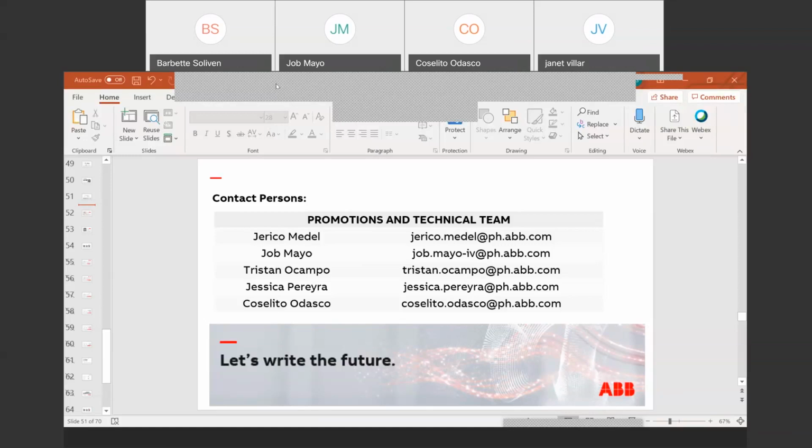So it's basically used for DC and AC. But for IEC 60898-1, DC is not tested. We have another standard for DC, so it's basically IEC 60898-2 for DC application. But for IEC 60947-2, it can be used for both AC and DC.